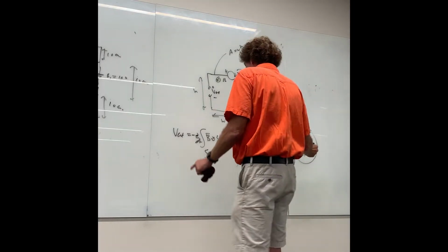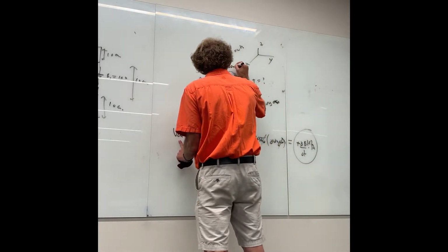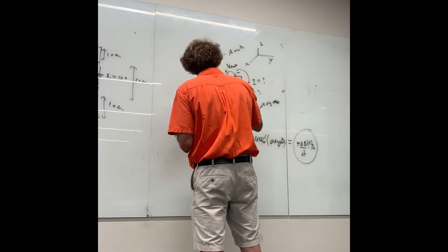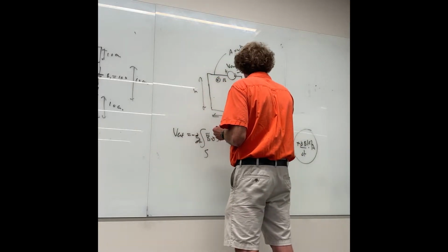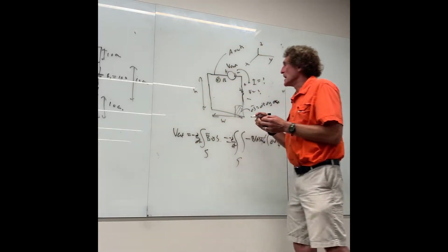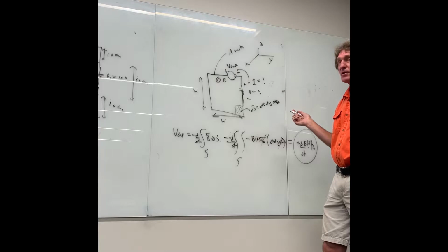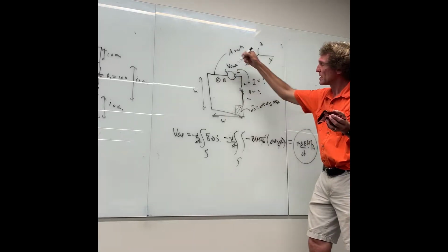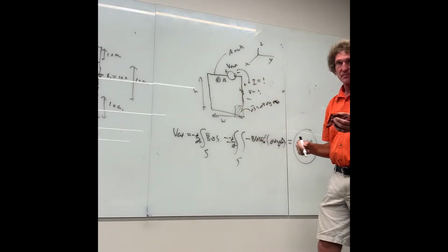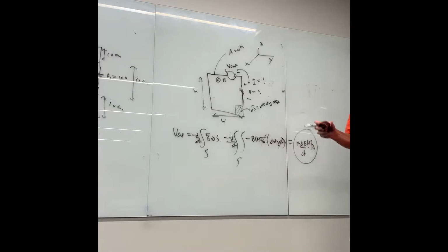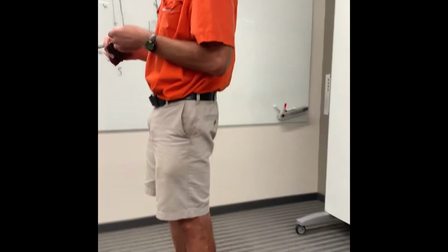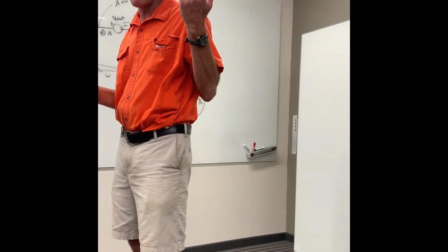This source voltage here, my VEMF, is going to go in there. And this is now going to get shorted. And now I put my resistor in there, R. And now I can get anything I want. But you'll notice the current is being driven counterclockwise here. All right? And it is a function of the time derivative. For us, the time derivative is just going to be what? That was 2t milliweber, so it's just 2, right?